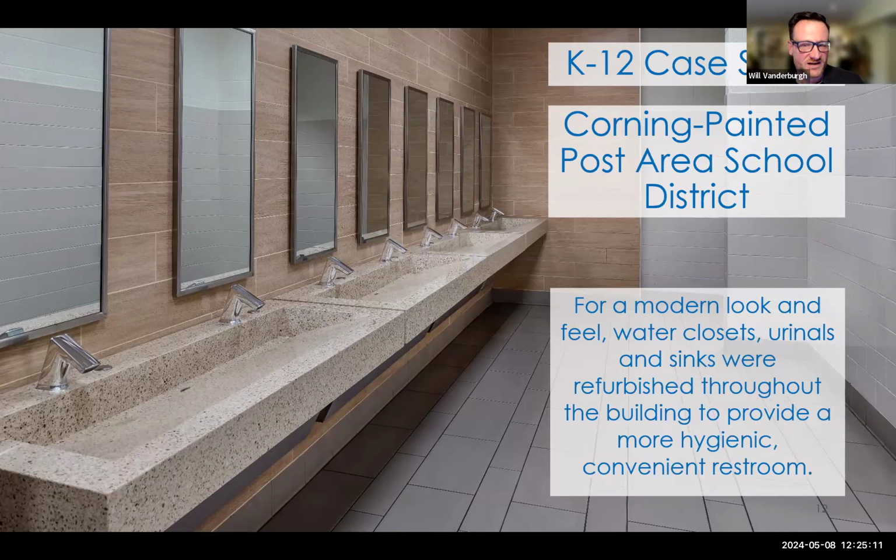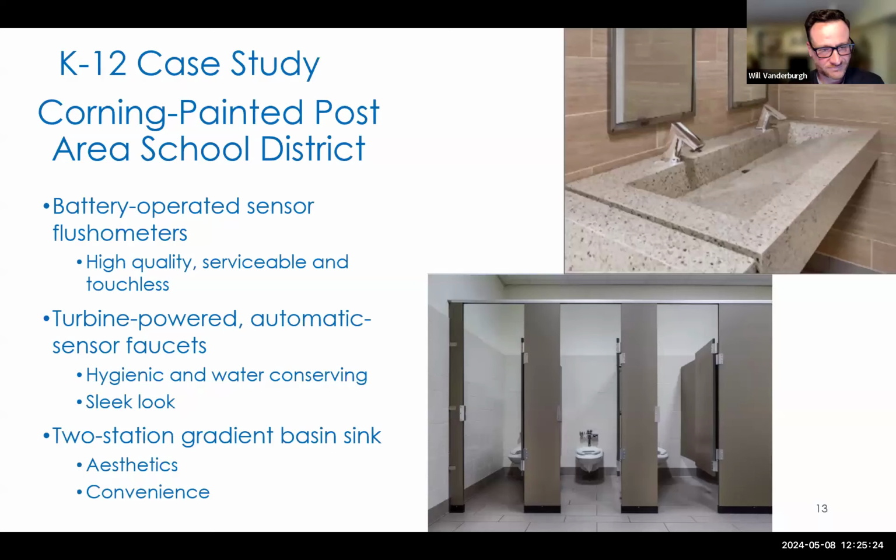combined with sensor activated faucets so that they could eliminate that touch of the faucet, because that is typically the most germ infested area of a washroom, the manual faucet. One of the things they did in the washrooms themselves is use a battery operated sensor flush valve. That way they didn't have to run new electrical to all of the different washrooms in the school, because it was a retrofit scenario.